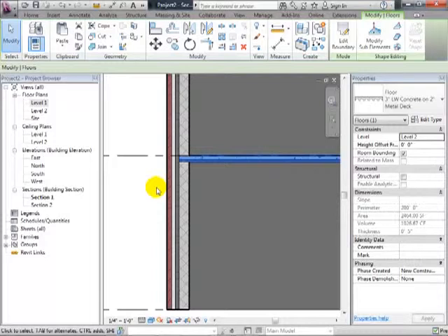These big section views, we'd like our sections to be as accurate as possible. The key here is really just editing or modeling as accurately as possible. The big thing typically is making sure that the boundaries of the floors and the boundaries of the wall core layers are all set up so you have the right intersections in terms of what's going on.